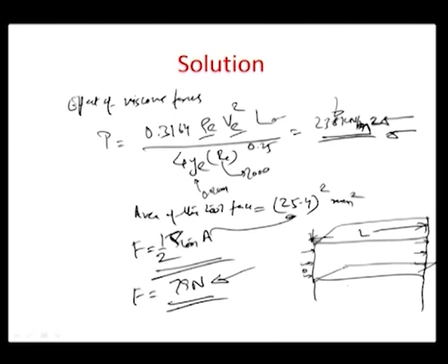Sometimes you have to compare the pressure values with respect to the ultimate flow stress of the material, and then you have to be very careful about one aspect: not only should the velocity be designed in a manner so that the electrolyte does not reach the boiling point, but also the pressures that are thereby imparted because of whatever velocity level the electrolyte is flowing through should not be able to warp or damage the surfaces which are being machined or the tool surface. So, these two are the design constraints for eventually determining the optimal velocity, with the temperature condition and the material condition of the tool as well as the workpiece material.